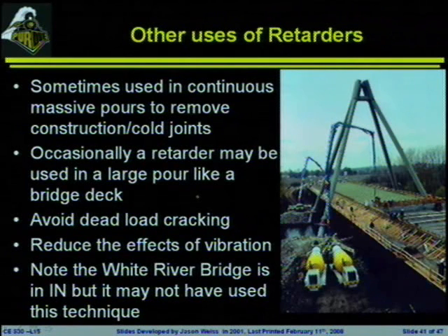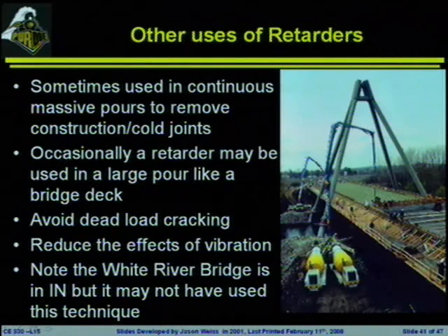So here you can see construction taking place over the White River. I don't know if this was done in this particular construction project. It was just sort of a nice picture. You can see the pumps taking the concrete from the trucks. So the basic idea here is that you would retard the initial concrete that's being placed. The rest of the concrete would be gaining strength much more rapidly, and the idea is that the entire concrete would start to set at about the right time.